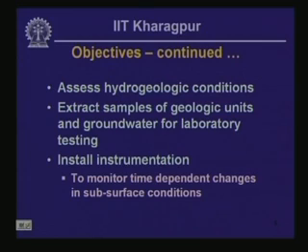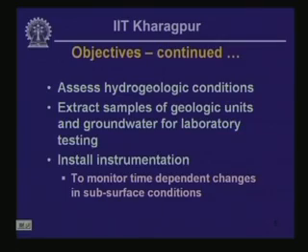For example, if the groundwater flow has a seasonal variation, then how the groundwater regime varies over time, we want to know that, whether it rises to the surface or what depth it actually falls to. This has implication in the design of a particular facility at that site. So these are the main objectives of a subsurface investigation program.